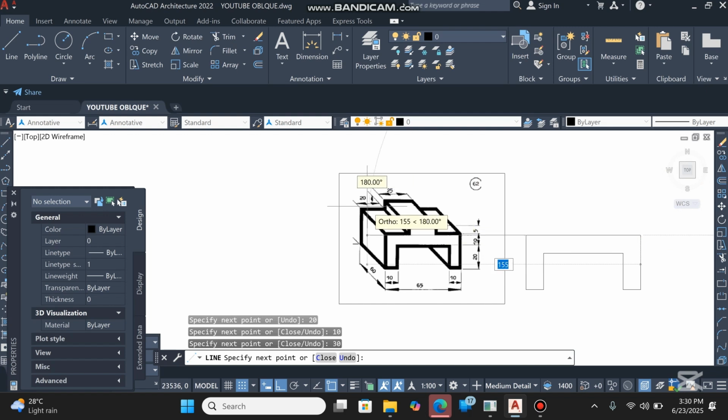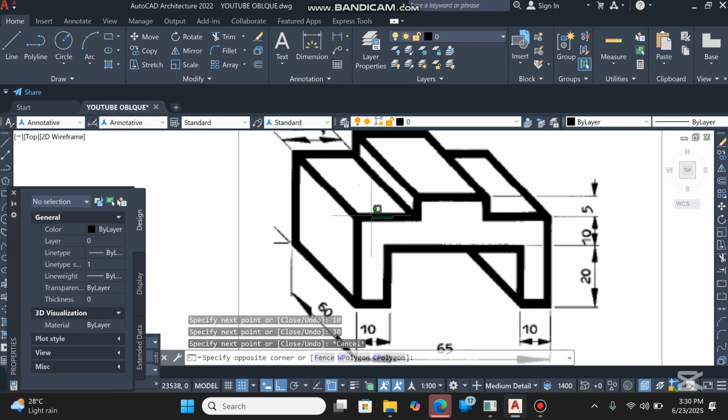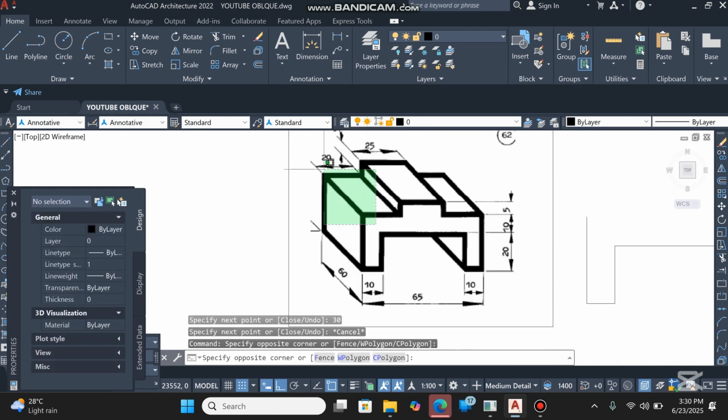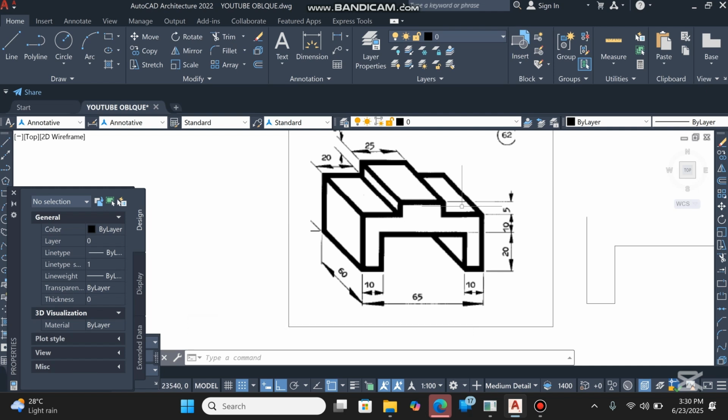Now it tells us that on the left side, this line right here, which I'm highlighting, would be 20 millimeters. It also means that the next side over here is 20 because they are equal. Again, if we would do some math, we know that the full width of the shape is 65. If over here is 20 and this section at the top is 25, we just have to add that and get 45 and just minus it from 65, which would give us 20.